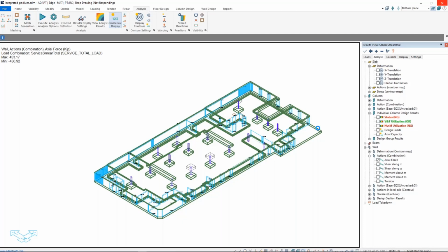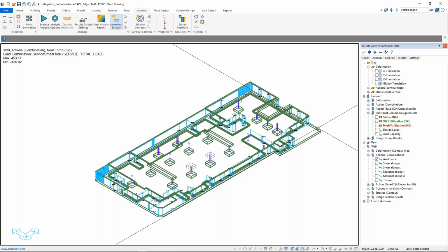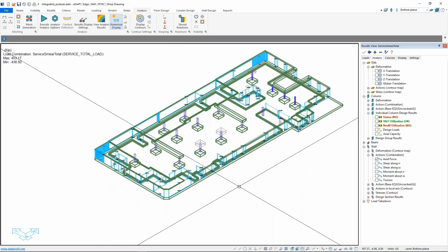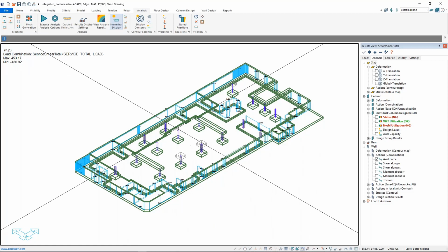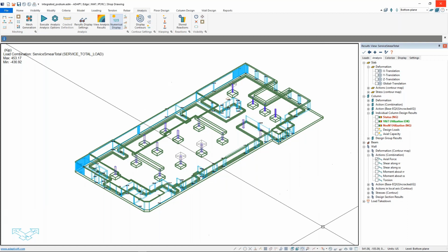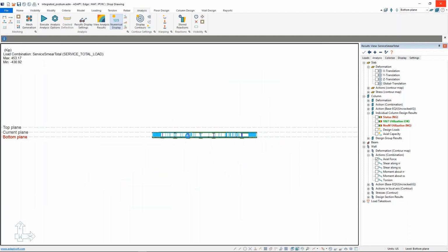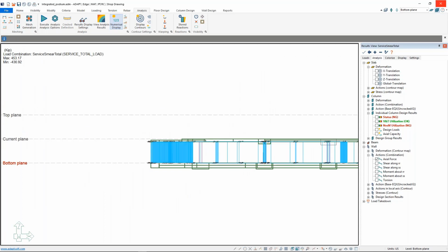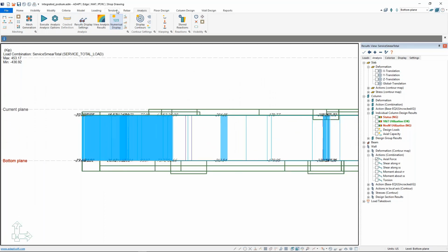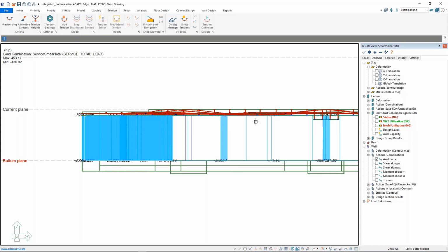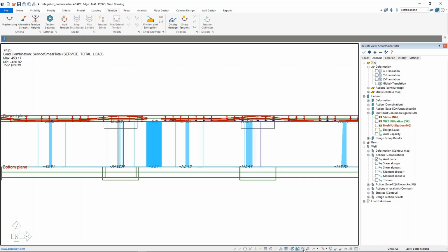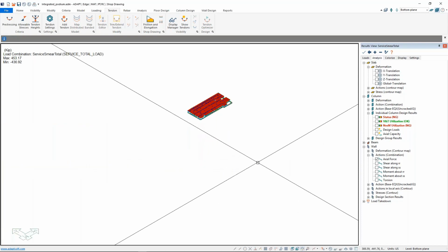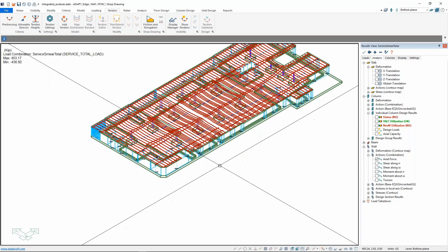Whenever I'm on these webinars, my computer runs a little bit slower. So now we're actually in the full mode. You see on the top right, I have my multi-level mode. If we look at this from the side, you can now see that this is the full concrete podium that we're modeling. And if I turn on my tendons, these are the tendons that I would have had in my podium. And then we're transferring those loads based on the process that I described down to the foundation.